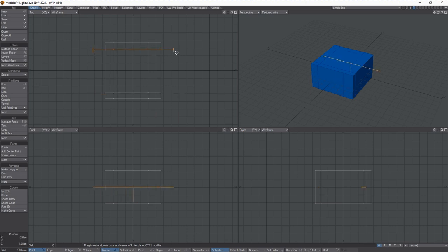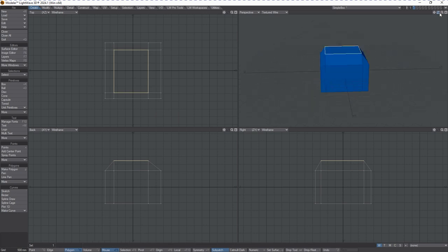and this will allow me to select an individual polygon. Go down to polygon mode, and we can select an individual polygon, and we can move this polygon around. So I'm going to hit T to transform that polygon, and then I can move it up, and now I've got a box that's got some push out to it. Now, this is going to cause some problems because these polygons here are non-planar, meaning they're not flat. So let's try something a little bit different.